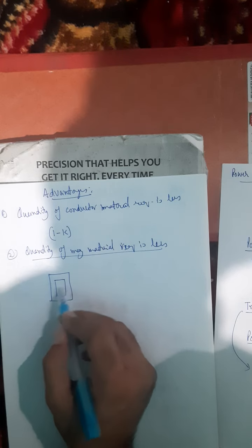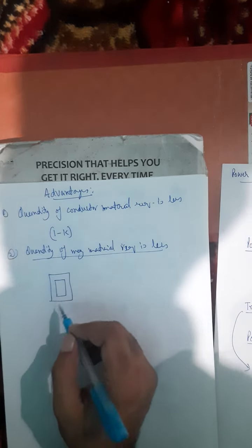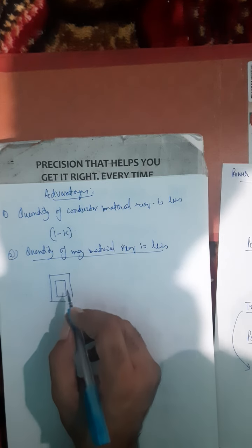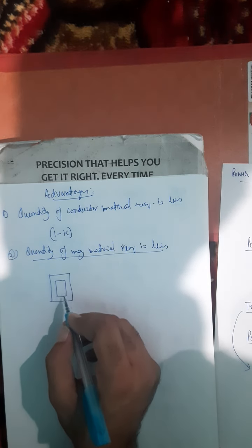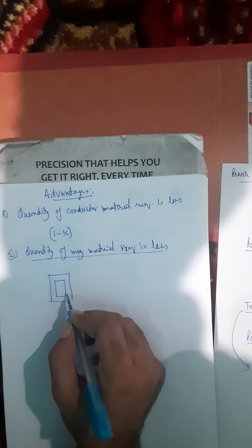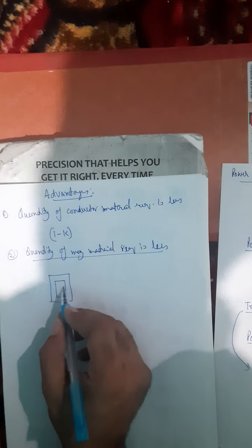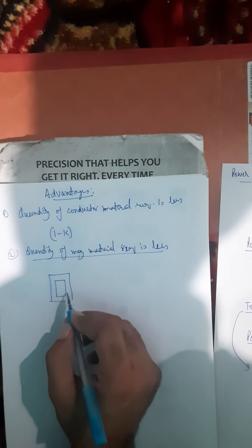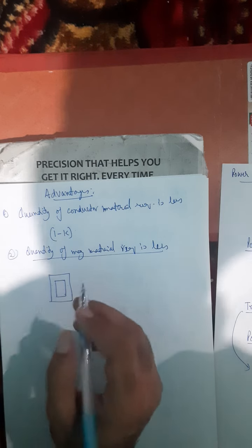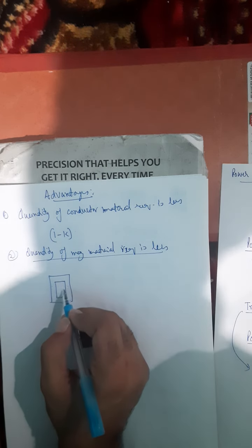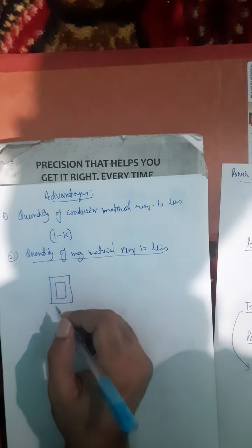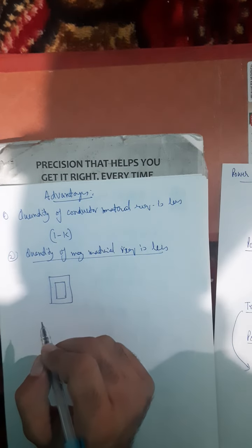If our conductor material is more, then we have to keep a bigger window, okay? So the window dimensions are decided from the consideration of insulation and conductor material. For an auto transformer, a reduction in the conductor material means lower window area, and therefore smaller core lengths are required. Reduction in copper material means lower window area, and lower area means smaller dimensions.